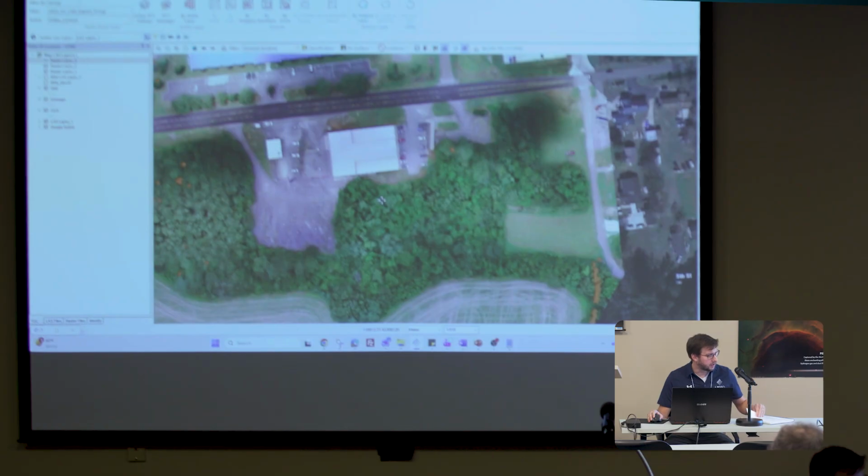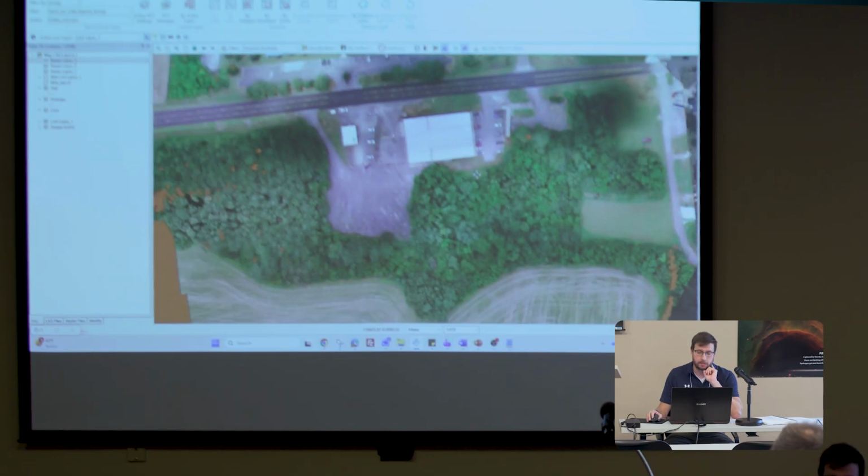The next part of this is tiling the ortho, and just full transparency, this is a really tricky operation, not just in our software, but in other software packages. One of the main downsides of using a shapefile grid for doing this is that typically you'll see a little pixel gap between the images. When I presented this last year in the version of LP360 we had, I was able to produce this with no gaps. But in this current build, I'm seeing some kind of issue. So you're going to see those gaps, but I'm still going to review the workflow with you, show how it works, and at some point in the future that'll be resolved.